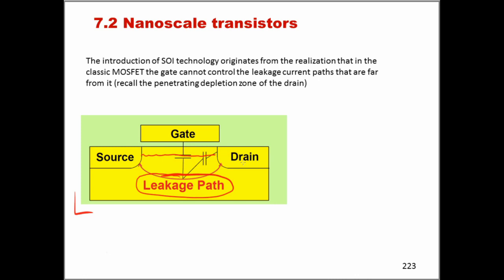So the SOI technology has been introduced to try to tackle this problem, to try to make sure that the gate is in complete control of the piece of silicon that represents effectively the channel of the transistor, and there is no part or no region of this piece of silicon that is not under the direct influence of the gate.